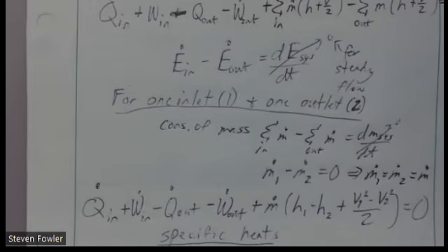If it's a turbine or compressor or any other generic control volume, we said, all right, can you find the speeds? Is it asking for the speed change? Or are the speeds given to you? If the answer to all three of those is no, then you're probably just going to neglect that kinetic energy.